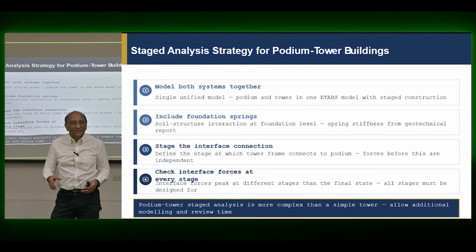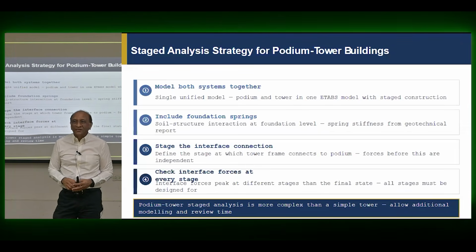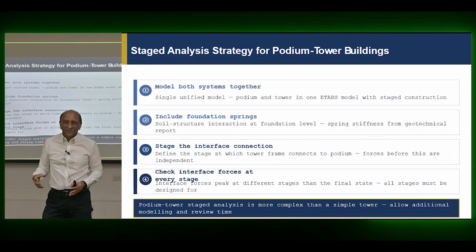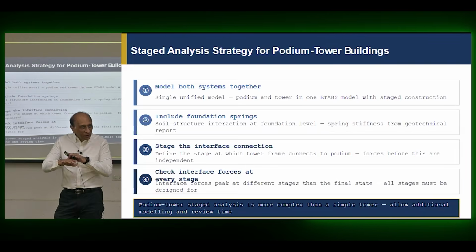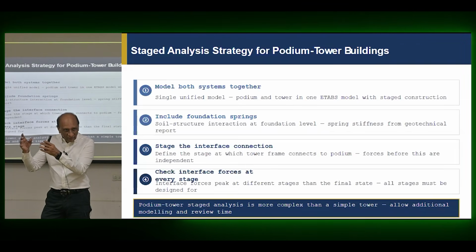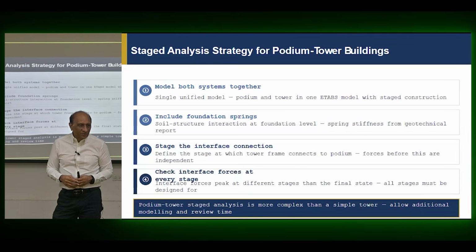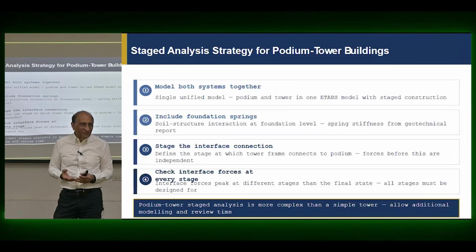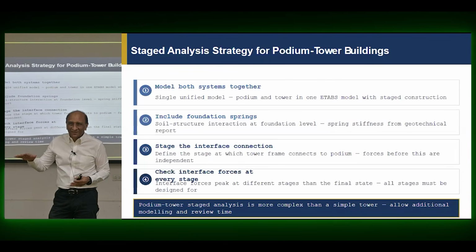It is only recently that they created this, where you can create each tower with its own diaphragm and separate them from each other. Otherwise, you get one mode shape, you get one everything. So even if you were able to model 5 towers, ETABS internally will consider them to be one big building, invisibly connected by a diaphragm.